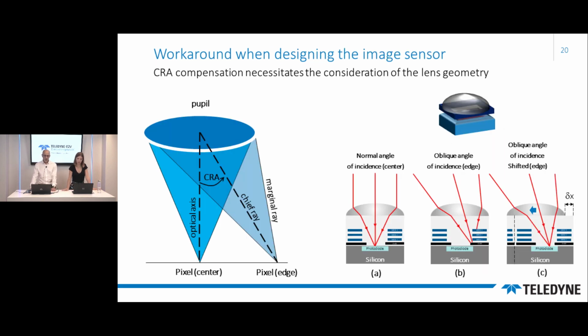So there are also design tricks. As shown in the figure on the left, the light rays concentrated by the pixel at the center of the array form a solid angle, or three-dimensional cone, that is bounded by an angle to the normal plane called the marginal ray angle, or MRA. The central ray of the solid cone is called the chief ray.